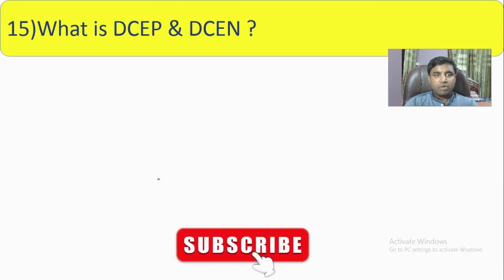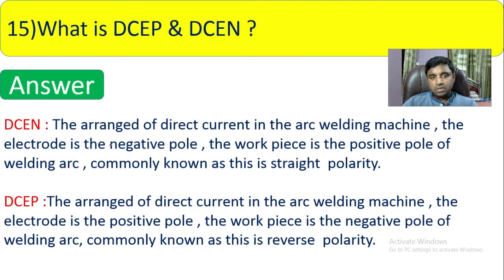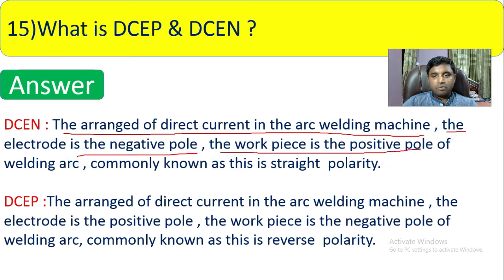Question number 15. What is DCEP and DCEN? This is a very important question in welding. You arrange direct current in the arc welding machine. In DCEN, the electrode is the negative pole and the workpiece is the positive pole of the welding arc, commonly known as the straight polarity. So always remember, in DCEN the electrode is the negative pole and the workpiece is the positive pole. That is called the straight polarity.